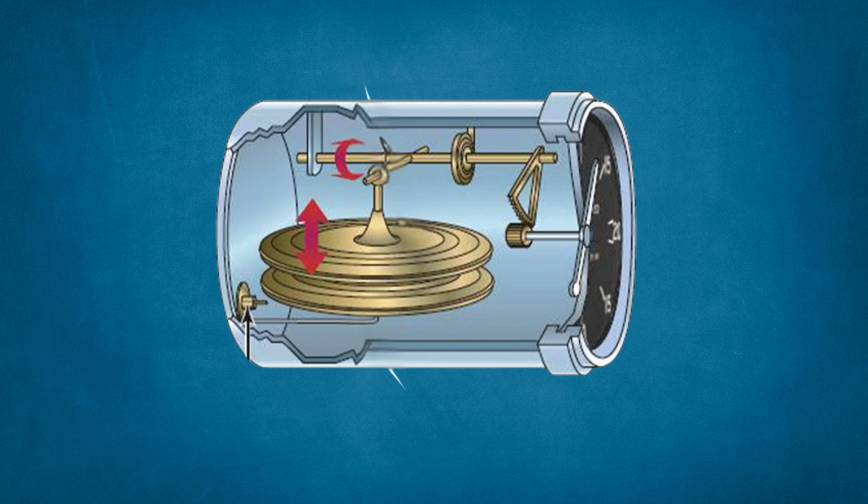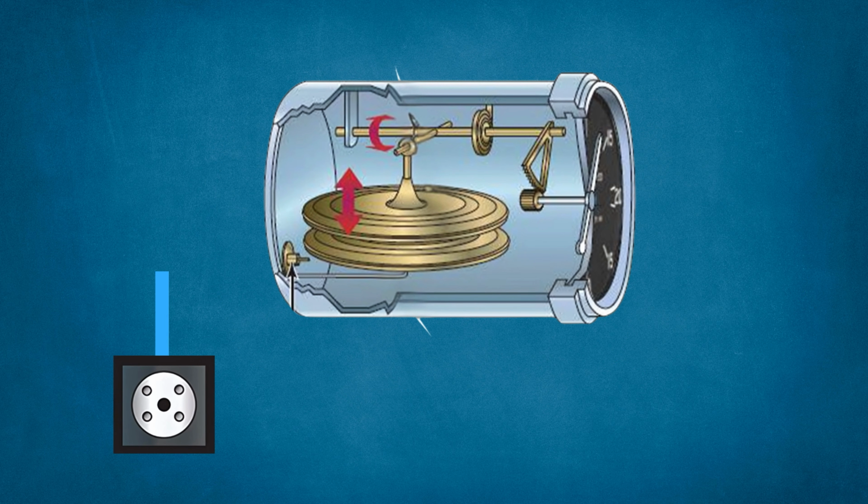In the vertical speed indicator's case, the static pressure enters the instrument through the static pressure line that you can see in the diagram. This line connects to the inside of the diaphragm. The static line also has a restricted hole that leaks pressure at a calibrated rate to the instrument casing. Both of the inputs come from the static port, but the inside of the diaphragm has an unrestricted opening, and the vertical speed indicator case has a metered opening.